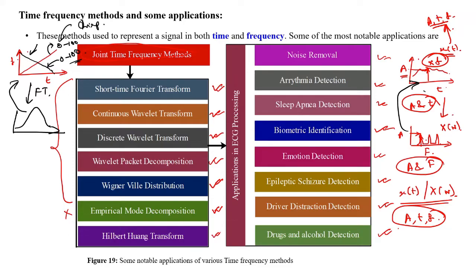No. Usually Fourier series is used for the periodic signal analysis. Fourier transform is used for the analysis of both periodic and aperiodic signals. Now, why is that so? Usually you will find that many students say Fourier transform is used for aperiodic signal analysis. That is so because it is considered that any aperiodic signal is periodic in nature as time t tends to infinity.